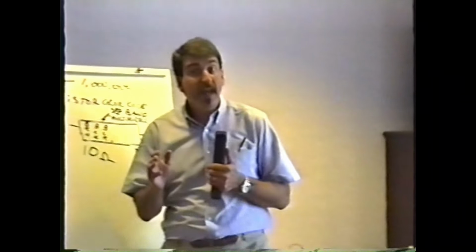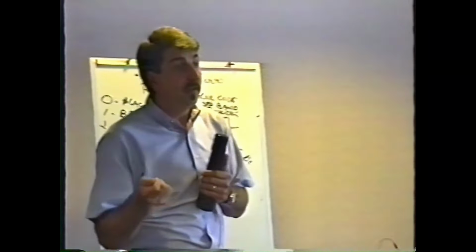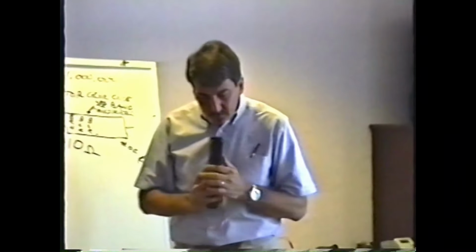Visual inspection, by the way, is critically important. It's really important to look at things. I find about half my problems just by looking at them. That's why if you're in a dark location, it's really important that you have a good trouble light. This business of having the pen light flashlight in your mouth and trying to work on something like this, that's nonsense. You really have to have a good strong light to be able to see what you're doing.